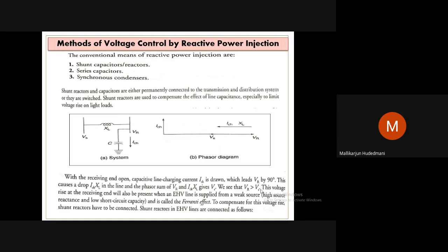We see VR is greater than VS in this particular notation. So this way we can see that due to the absorption of inductive or lagging VAR, we need to compensate by adopting leading volt ampere by capacitor. Suppose load is suddenly removed, which was already compensated by a compensator, we need to absorb it either by hooking up an inductor across a particular bus or eliminating the capacitor in part.